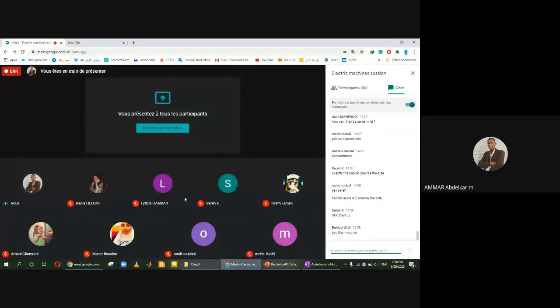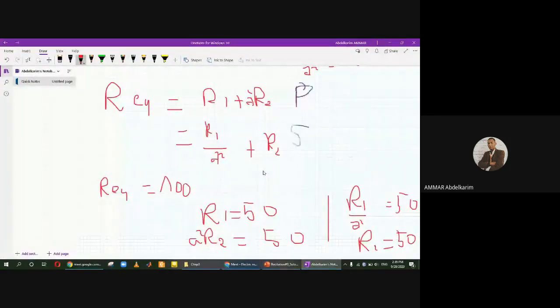If your measurements and calculations are correct, you can even do it with both methods: you calculate in the primary and in the secondary. But you should respect the impedance transfer from the primary to the secondary, and the referred equivalent circuit. That's it. For example, in the calculation of R1 and R2, the approximation will give us the same result.